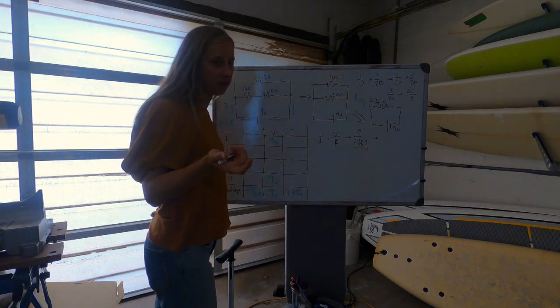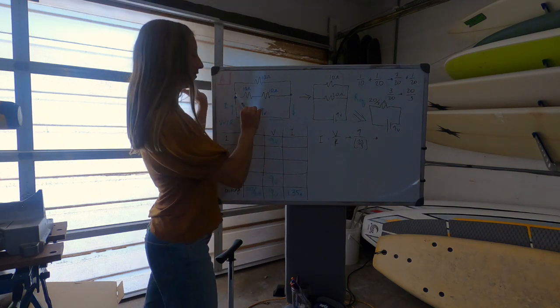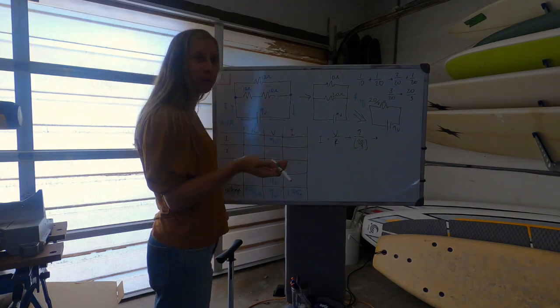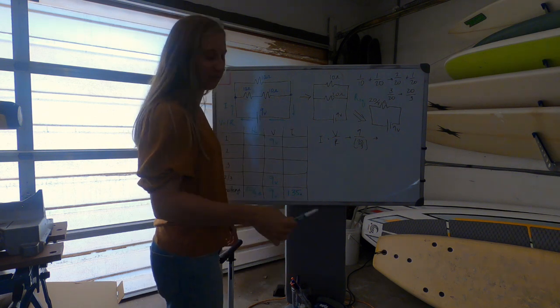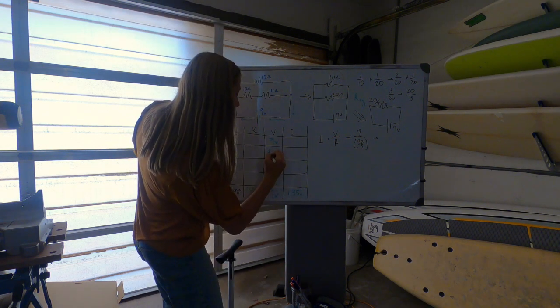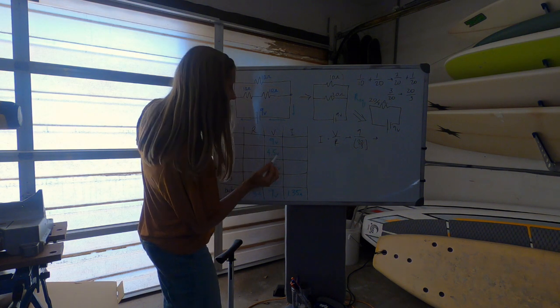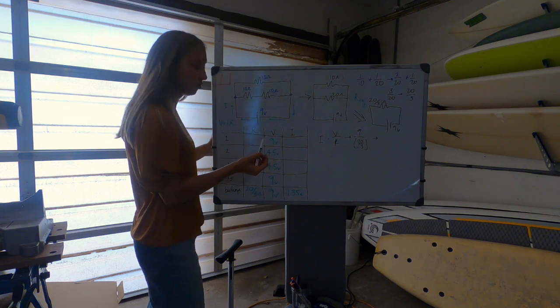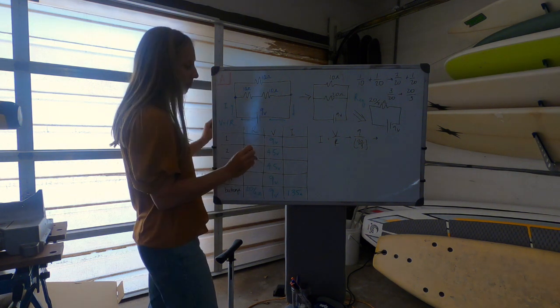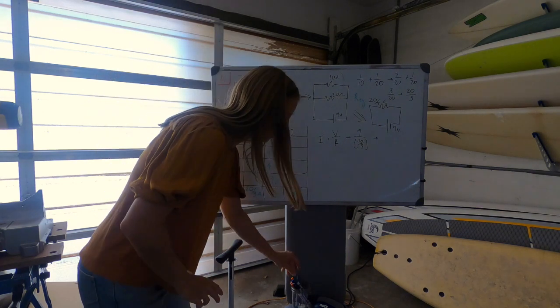And you can probably already figure out what each of them will be. If they have the same resistance and the drop for the whole thing is 9, then what would be the drop for each one? Well, it'd be half of that. So this would be 4.5 and 4.5. If these had been different resistance values, then we would have to do a little bit of math, but it's straightforward for this one.